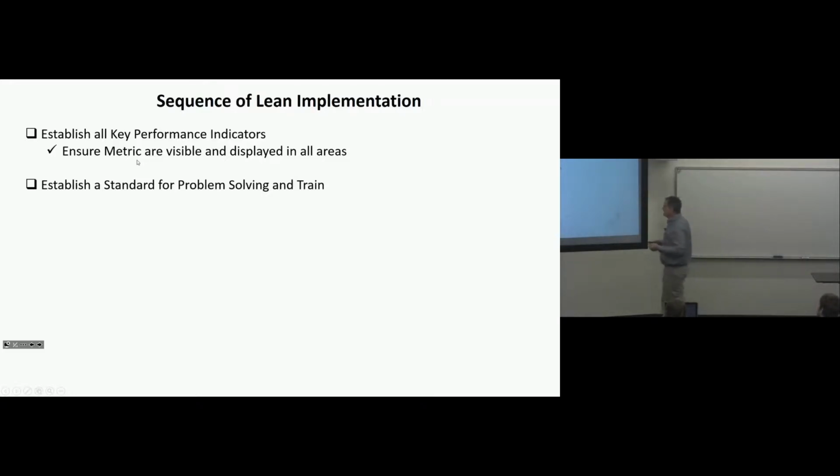So wouldn't it be a good idea to say, hey, we're going to be doing this lean thing and we would like the maintenance organization to use the 5Y method, and we're going to train you on it. It's pretty simple. For every time we have a machine down more than a half hour, you must complete a 5Y analysis. That's pretty powerful.